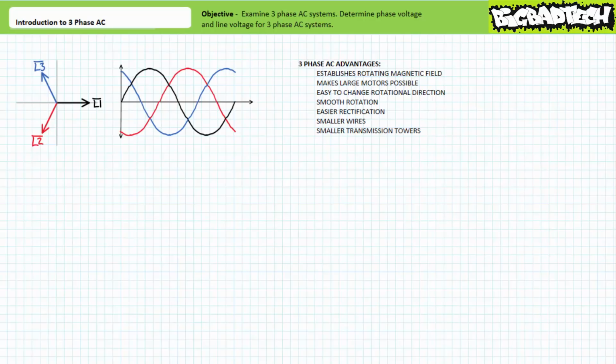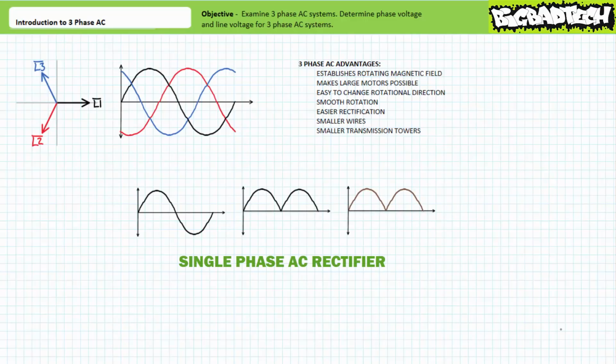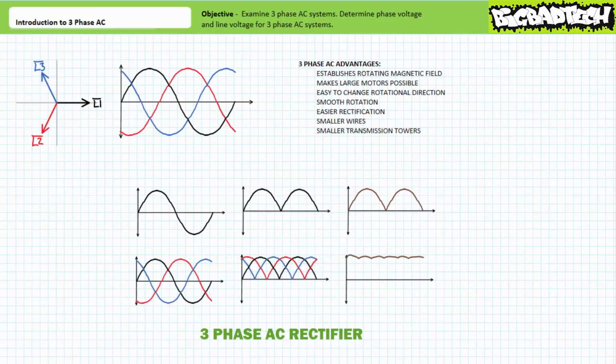Three-phase AC motors, because they're guided by a rotating magnetic field formed of 3 voltage phases, rotate smoother and exhibit less cogging, which is jerky, step-like movement. In keeping with this smoothness theme, power electronics devices like rectifiers, which convert incoming AC to DC, exhibit notably pulsed behavior when operated with single-phase AC and require extensive work to clean up the output. However, three-phase AC rectifiers produce notably smoother DC output and necessitate less work to clean up the output.